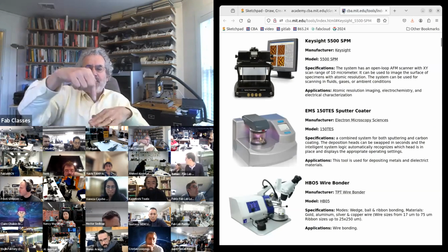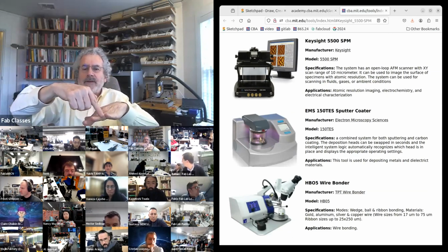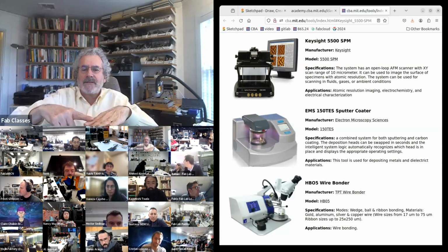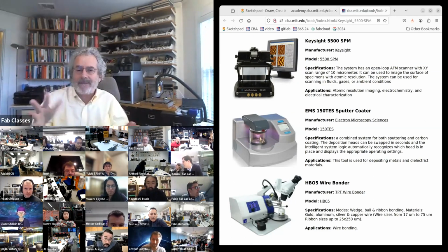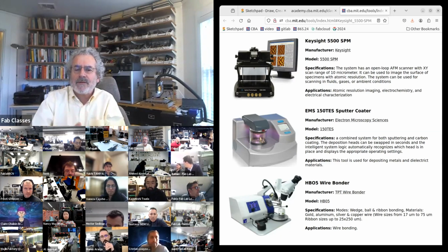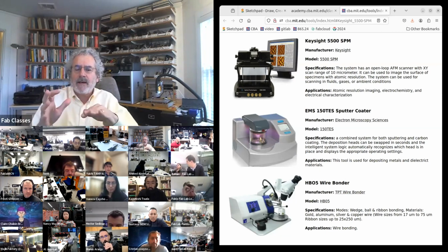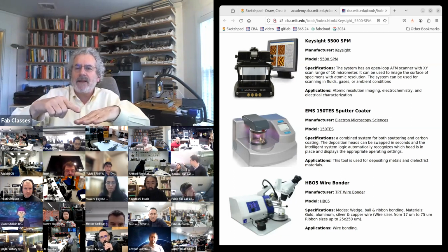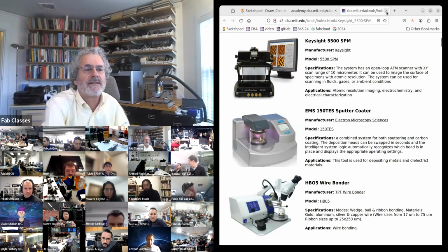This is an atomic force microscope. It has a probe that it drags over the surface, and it measures the surface at atomic resolution. You can do that at less than atomic resolution. So these are completely immune to surface artifacts, very high resolution, but it's not arbitrary 3D geometry. It's 2.5D, meaning it's giving you Z as a function of X and Y. So that's scan probe.